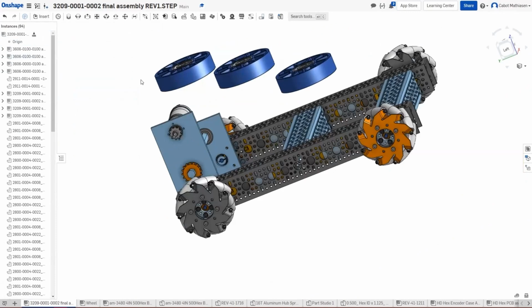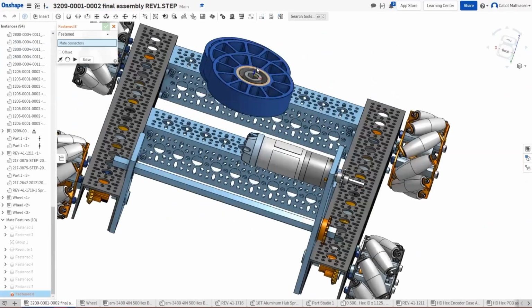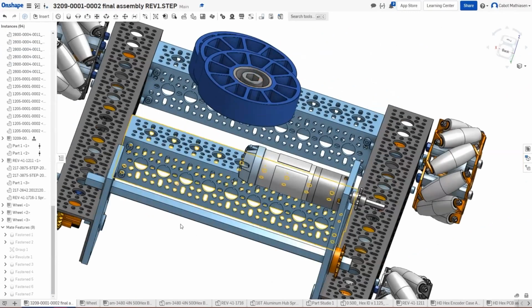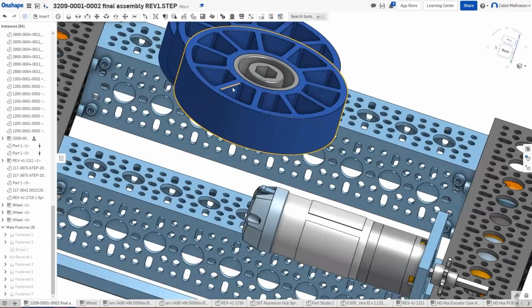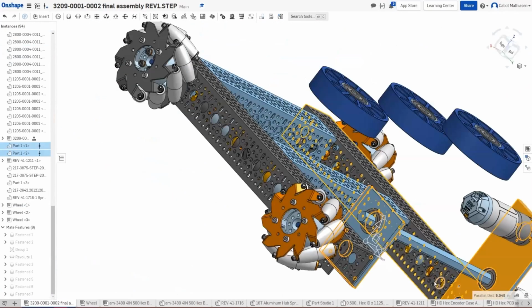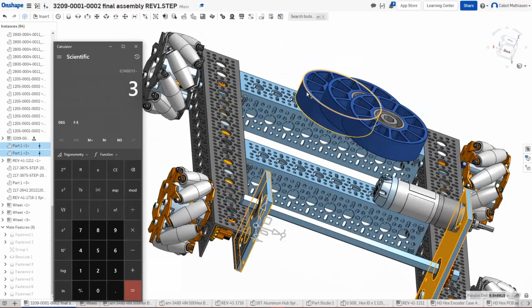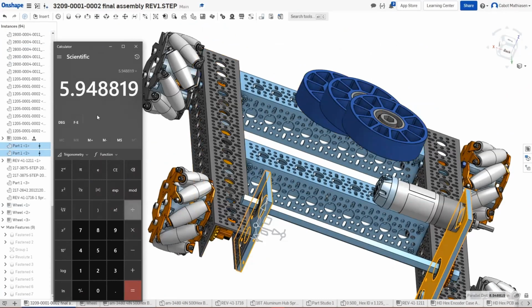Now here's something that I like to call math time with Cabot. As you can see, these are 1 inch in width and this is 8.94 inch parallel distance. So we take the 8.94 parallel distance, we subtract 3, 1 inch per wheel, and then we divide that number by 4, so we have 4 equidistant spaces in between, and that's how big the offset should be in between each wheel.